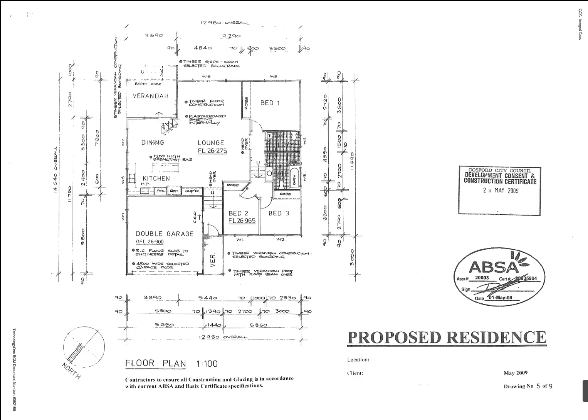Okay, well, we've got a 2100 wide sliding door there. So when we look at the window schedule, because the windows are generally aluminium and the sliding doors are aluminium framed, the code would probably be SD2118. Beg your pardon.